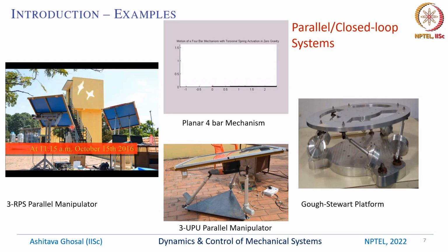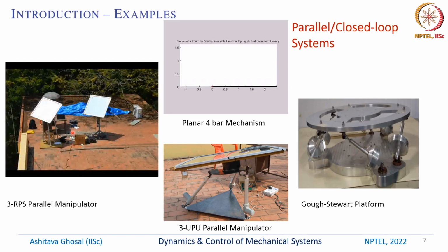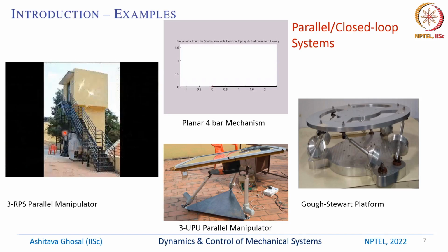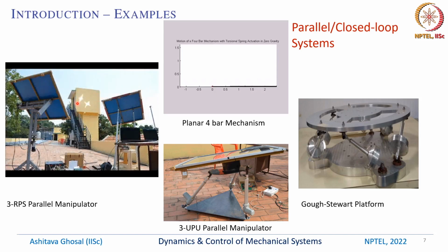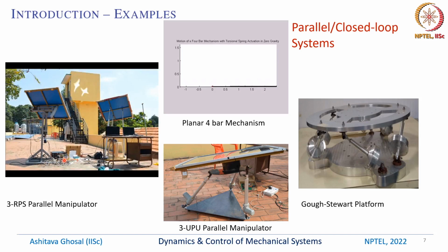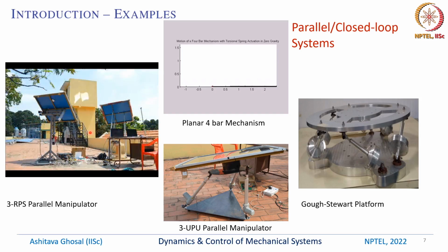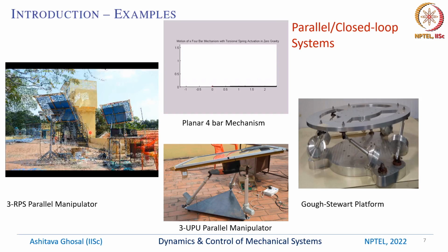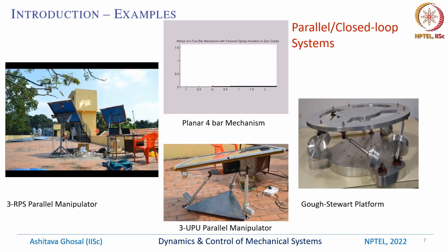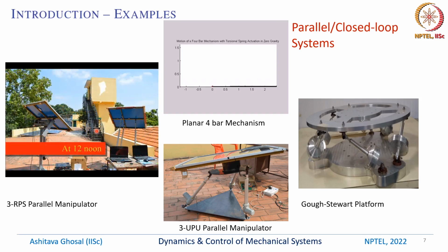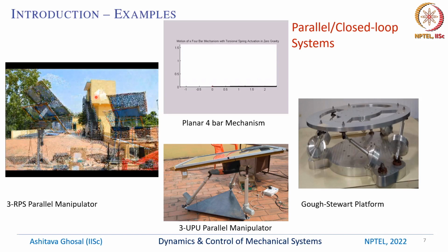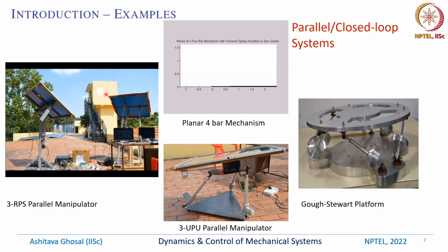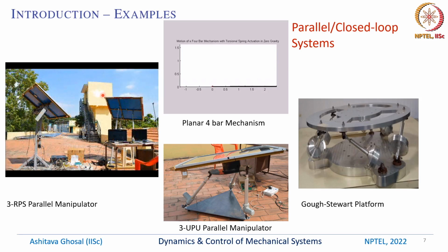This video shows how these 2 different mirrors, also called heliostats, move so as to focus the incident beam onto this receiver. And remember, the sun moves in the east-west direction and a little bit in the north-south direction. So the motion of these mirrors is not straightforward. It is not about one axis. It must rotate about 2 different axes. As you can see, both the mirrors are trying their best to focus. There are always some errors in manufacturing, but nevertheless you can see both the beams are almost at the same place.